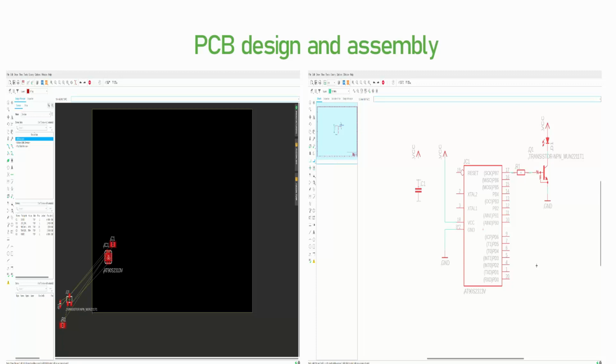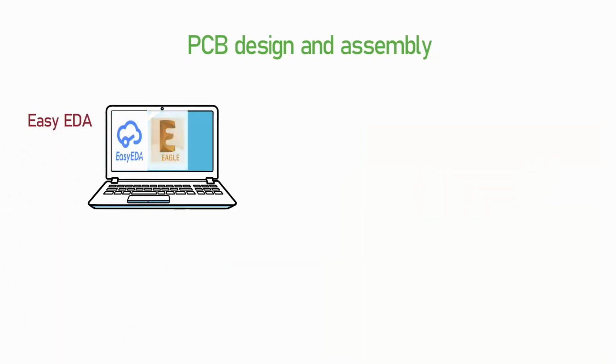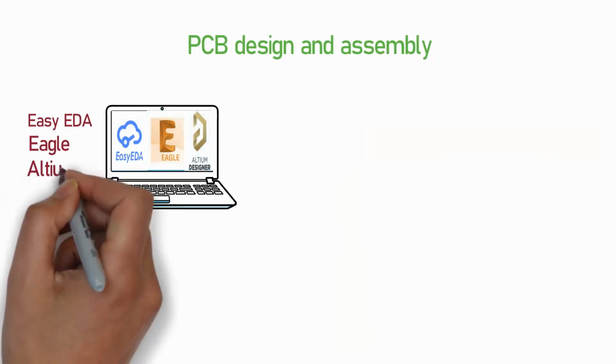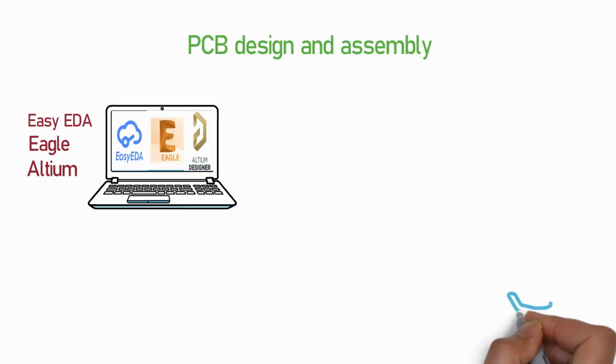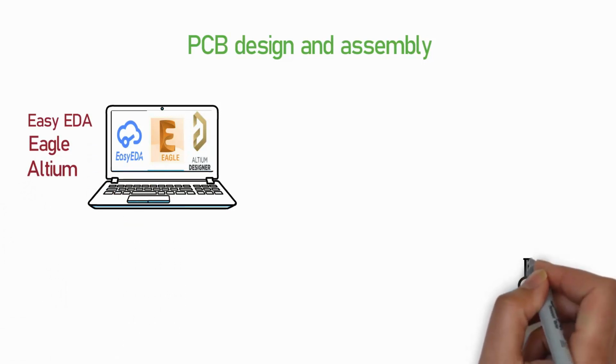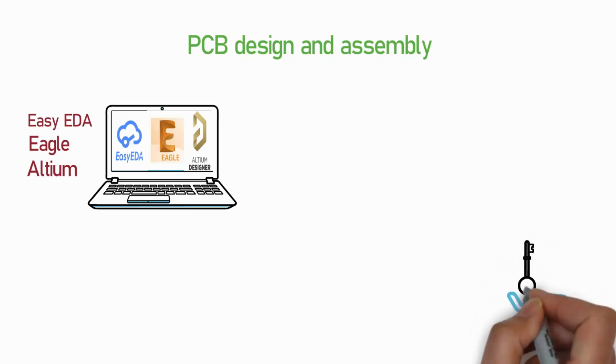There's some good, free layout software online such as EasyEDA, something affordable like Eagle, or up to expensive software like Altium. This step also needs a little bit of EE knowledge. When all of your schematic nets are converted to the PCB file, then all the components appear, and you need to place them in the correct position. Your EE experience comes in handy here too.